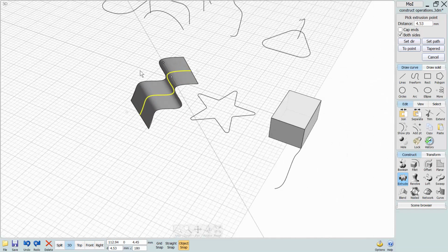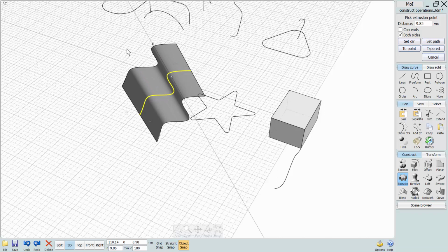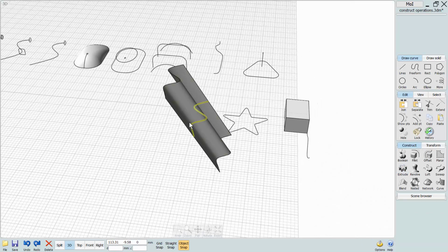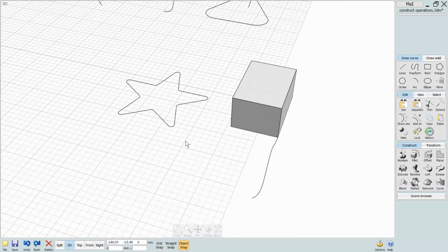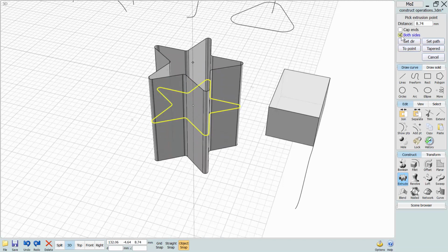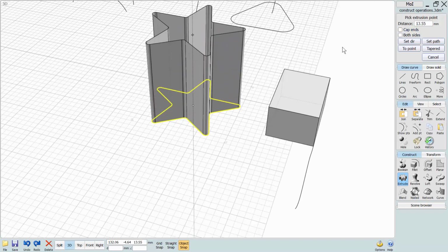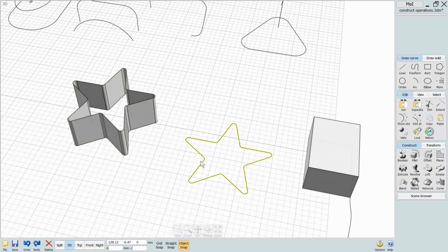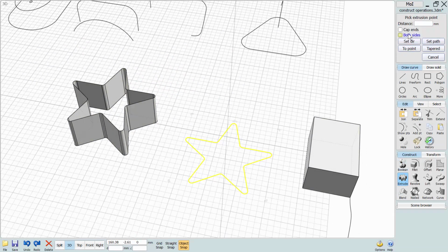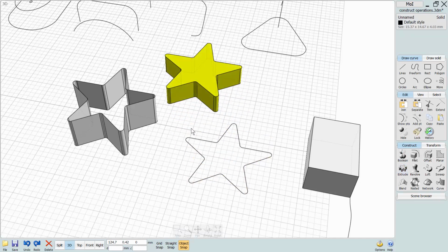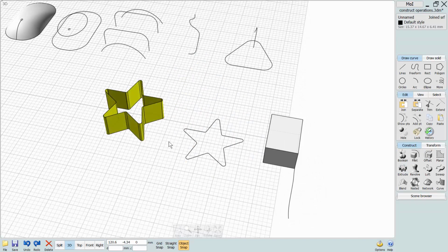So this is like a snapping guideline for this extrude operation, and you can go only in that direction. So that's how you lock it to a specific direction. Okay, so let's move to this one. If you use extrude in this case, let's uncheck this both sides option. Let's check this cap ends. So without cap ends, Moi will produce this surface, so have those two openings. If you select this and go to extrude and hit this cap ends option here, Moi will cap all those openings, and you have solid mesh in this case.